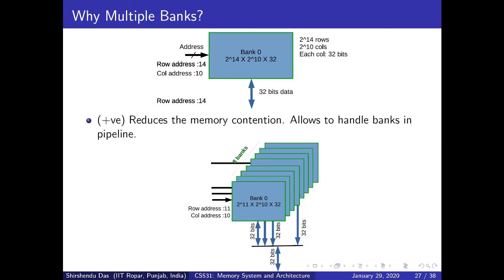So all this work, activating a particular row and moving the information from the row to the row buffer, is internal to a particular bank. One more thing I have not explained here is, they are sharing a common bus, but don't think that they are sharing a sense amplifier also.